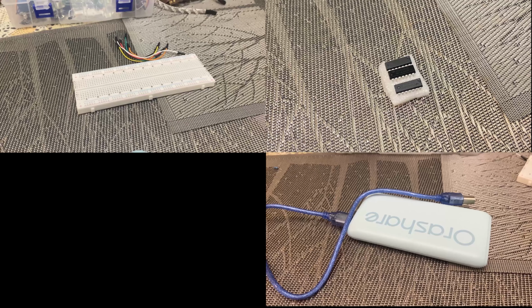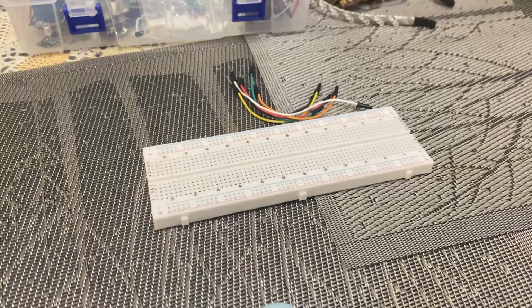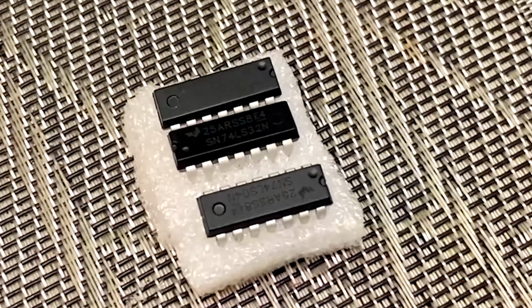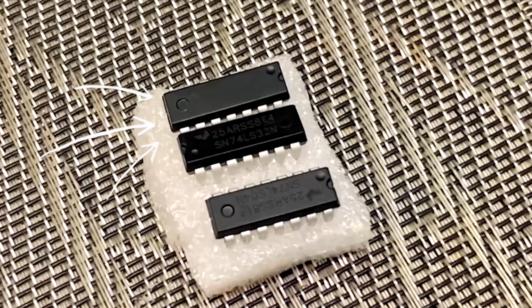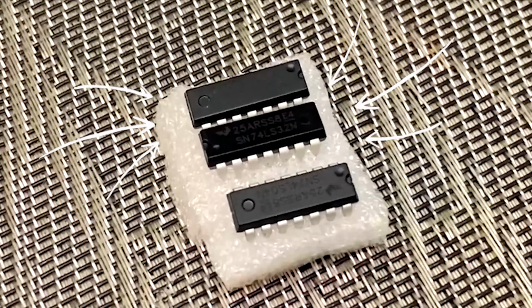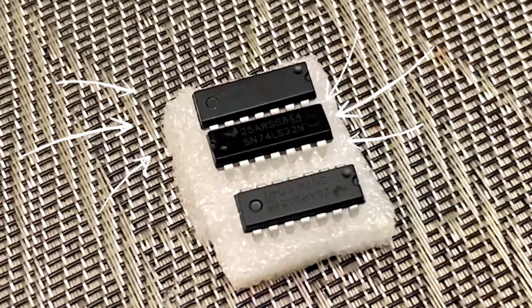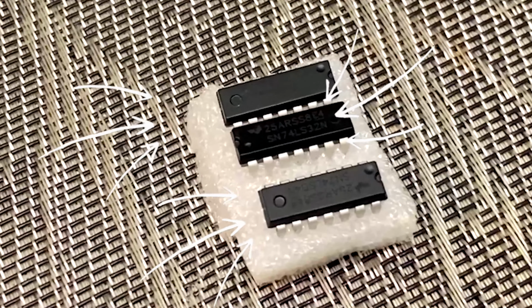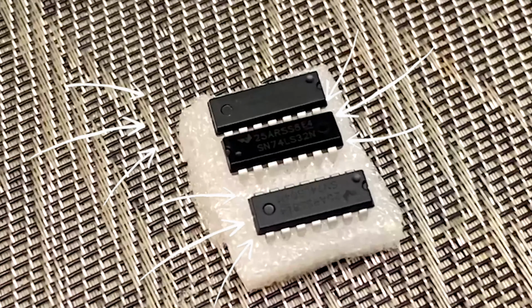These are the materials we will be using: a breadboard for connecting components, and jumper wires for linking our circuits. We have three integrated circuits: the IC7408 for AND gate, the IC7432 for OR gate, and IC7404 for NOT gate. Each IC contains multiple gates that we can use.